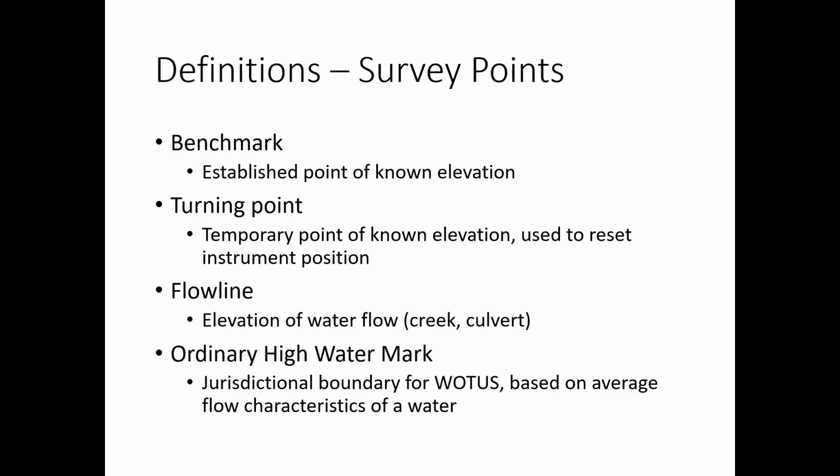Somebody has gone out there, figured this out before us, or it can be an assumed point of known elevation. We can assume an elevation and go from there. But that's what we base basically all the other elevations off of. I didn't put it in here, but we'll talk about it in a little bit. A turning point is a temporary point of known elevation used to reset our instrument position. And again, we'll get into more detail of that.